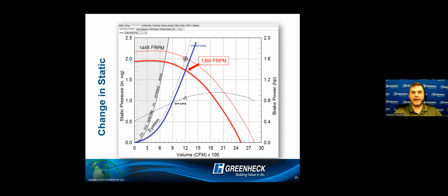Now, this entire exercise that we just walked through here of this example was really about having you see a fan curve the way I see it. Everybody sees static lines when they look at these beautiful pieces. What I see is what could be. Add a 1/4 or 1/2 inch of static pressure, or remove that. In my brain, I'm seeing those fan curves pull up and push down to different points of operation. So hopefully I can let everybody here see fan curves how I see them, kind of a living tool.